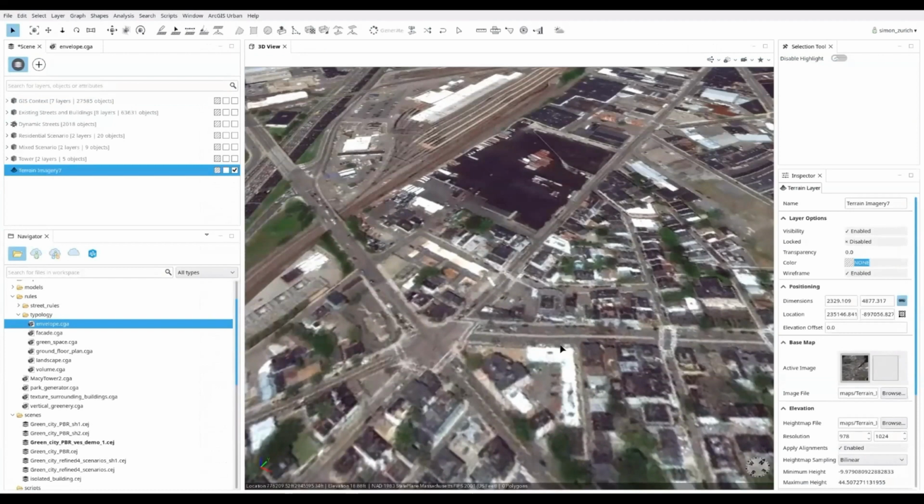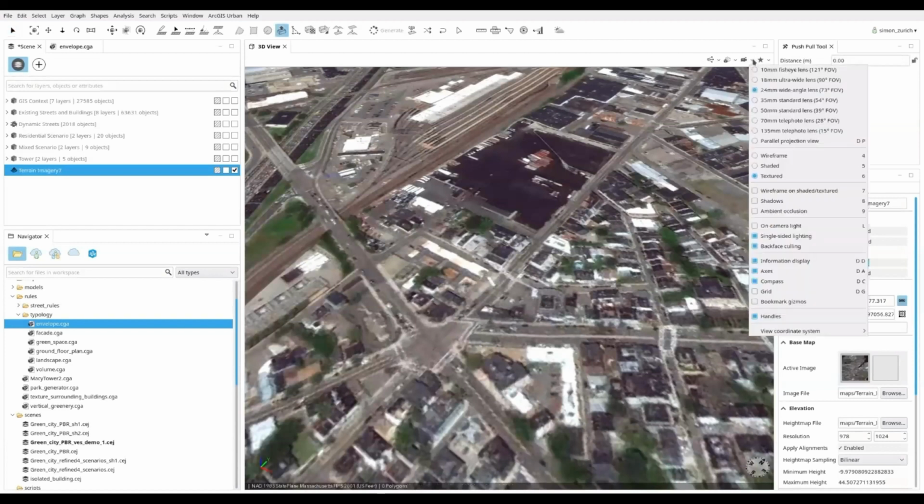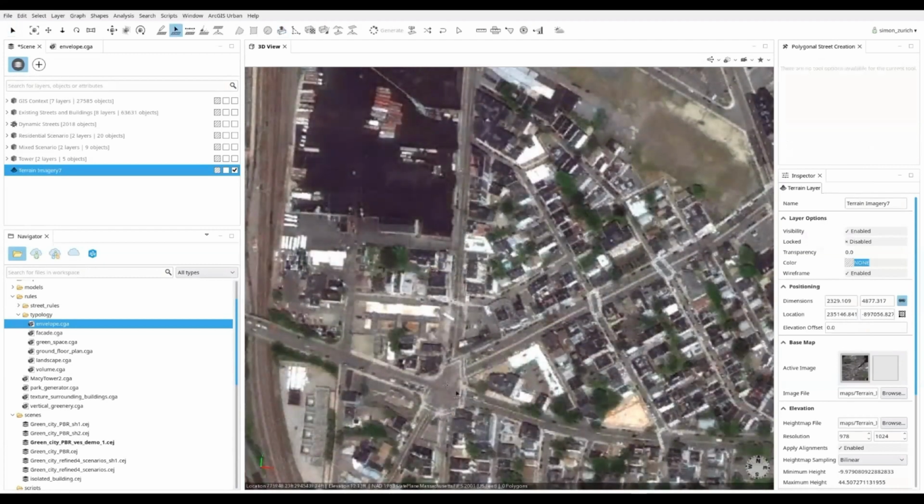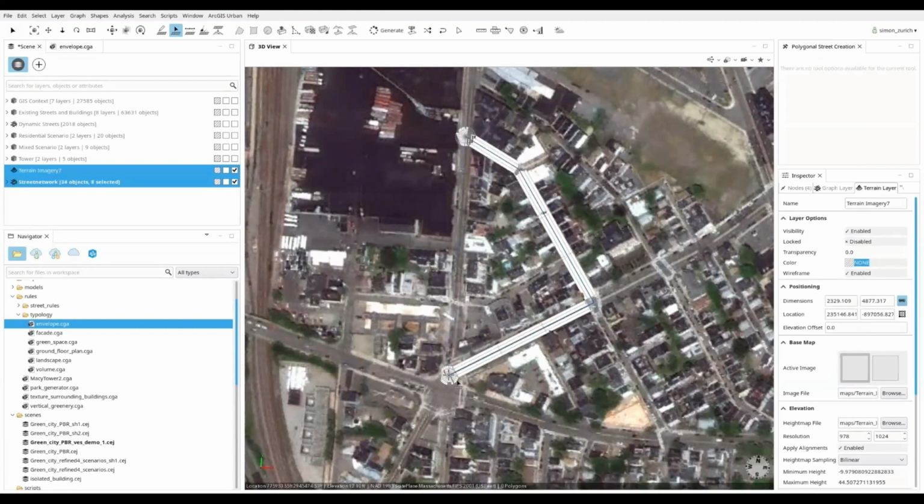On larger scenes, it's of course more useful to import the streets, but this might involve some more work to massage the data sources, as there are not really worldwide standards on how cities store their street data. So by placing the camera into orthogonal mode and pressing the Y key to look directly from above, we can start to trace the street.